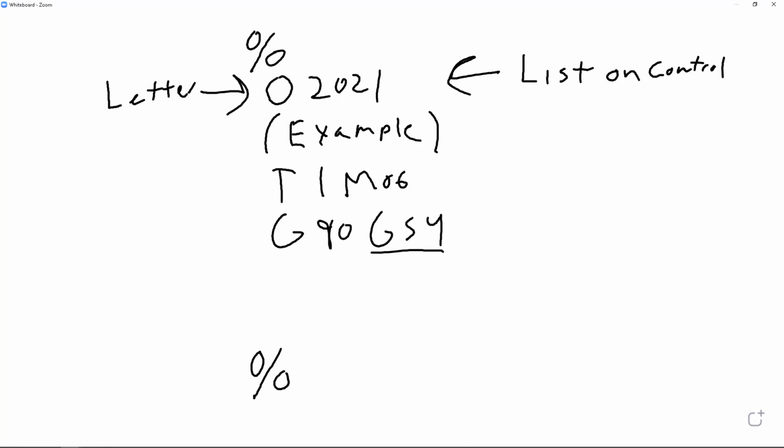All right. Then after that, you're going to have something that goes with a height offset, or something that controls the height in Z. Because G54, for what we're doing right now, takes care of X and Y. We still need a G43 comp. This is a height offset. We'll talk about that in a minute. Okay. You need to have an H value, all right, and then a movement, so to a Z 1.0. I know the text has 0.1. It's up to you.